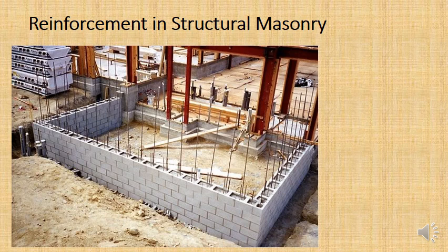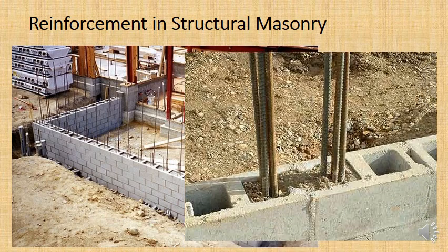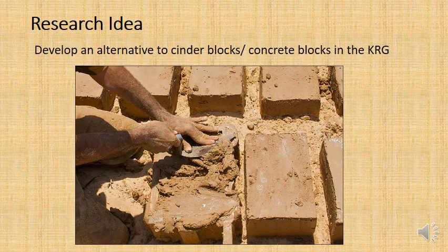And so that's going to give it good structural integrity in shear stress as well as compressive stress. So that's what it looks like. You've got these bars going down into the foundation usually, and then you set them in concrete inside that so that they're all stiff.